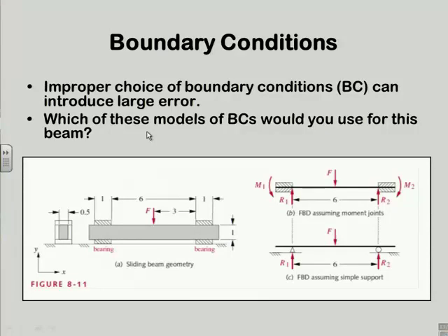And the problem is that my FEA modeler is very, shall I say, anal compulsive. If I tell it that those nodes are fixed, in other words, if I create that bearing by telling it those nodes along that length cannot move, by God, they can't move. There is no give whatsoever. But if I really buried that in concrete, the concrete could give, couldn't it?